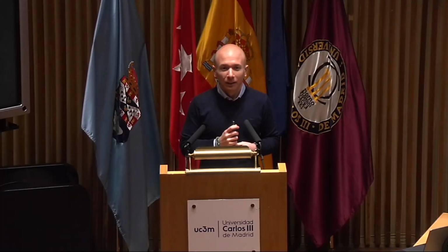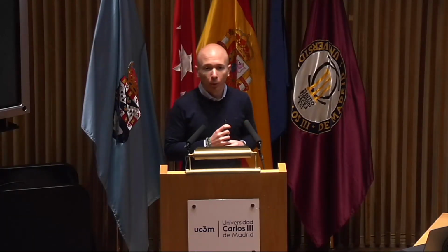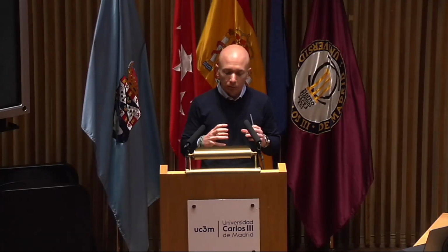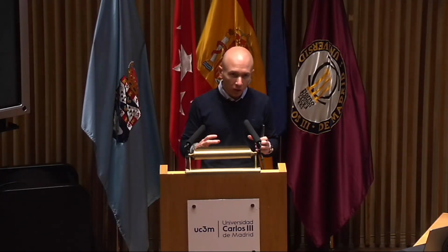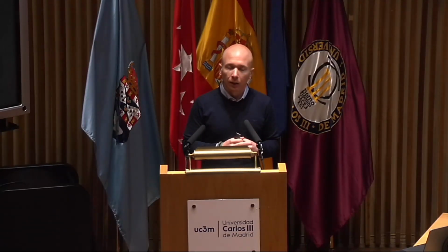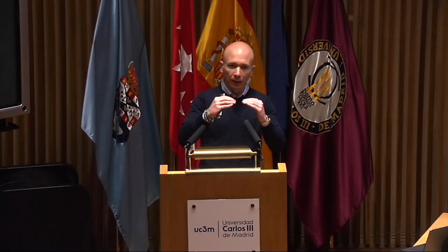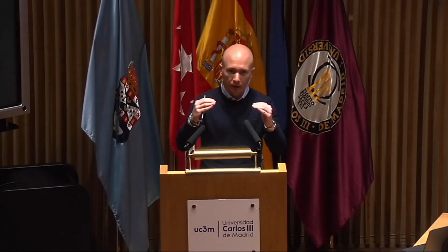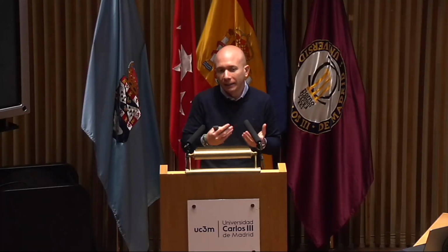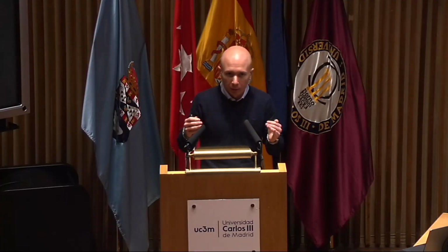That's my next step. The idea is to have a porous material somewhere, we don't know yet well where, to increase the band in which the liner works. It becomes a kind of multi-degree of freedom liner. This is an evolution of what we call double degree of freedom, where you have a cavity and within the cavity another perforated plate. In that case you create 2 peaks of absorption. Ideally, if you add the porous material, you expect a broadband response.